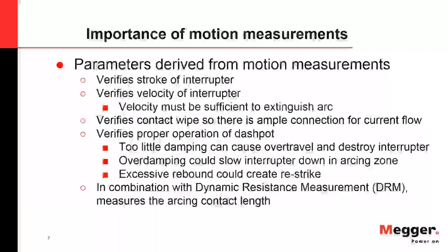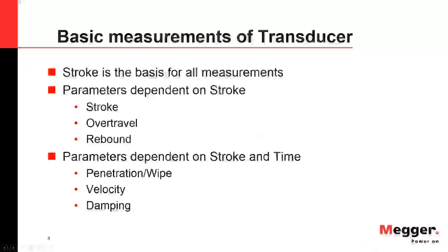And then some other applications: in combination with a dynamic resistance box, you can do your dynamic resistance measurements with velocities from the transducer to evaluate the arcing contact length of your SF6 circuit breakers.